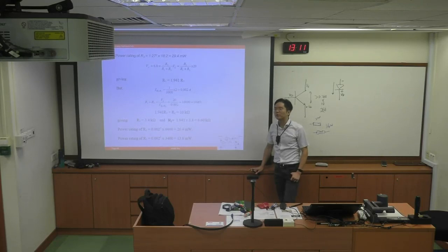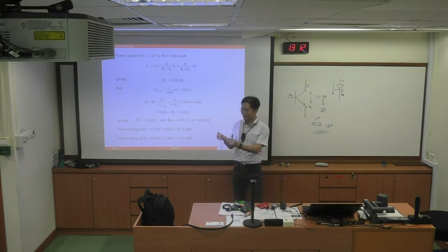That's also possible, but that'll be overkill because of the size. Typically I bring this 2-watt resistor, which is already pinky size, but it's too bulky for small microelectronics. So you just want to use the right size resistors for the right rating. But of course, theoretically, if you use the older, let's say 2-watt or even 10-watt compatible resistors, you can sustain it, no problem.